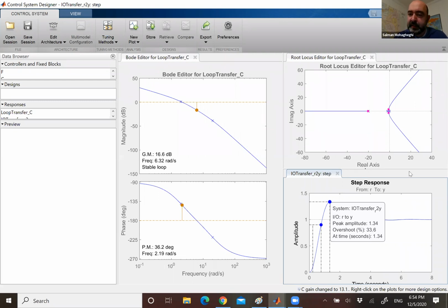And you should probably expect it, because notice that I have very little margin to play with the pole locations. If I increase the gain a little bit, the two loci corresponding to those poles cross into the right half plane, making the system unstable. So with just the P controller, this cannot be achieved. This oftentimes is the case: whenever you want to design a system, you usually start with a P controller. And then if you cannot achieve your design criteria, you move on to a more advanced type of controller. So the next option that I want to try is a PD controller.